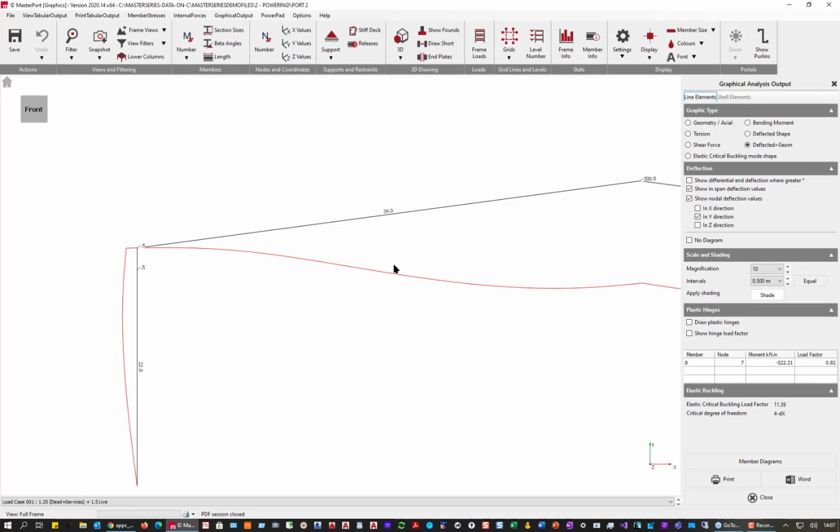And that's very useful in multi-story and things like that, because you're not interested in the top floor having all compressed by 150 mil due to the column shrinkage. You're interested in the curvature of the beam for your services. So yes, we do both.